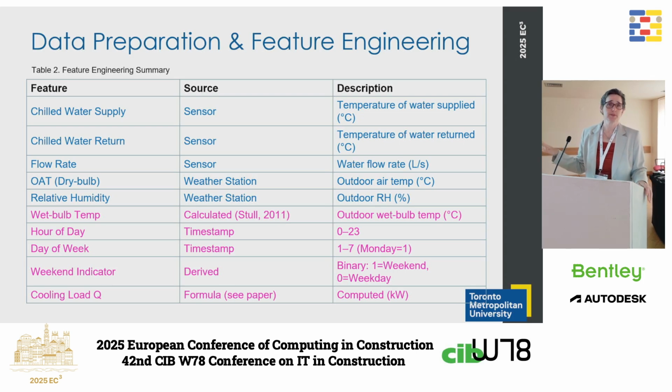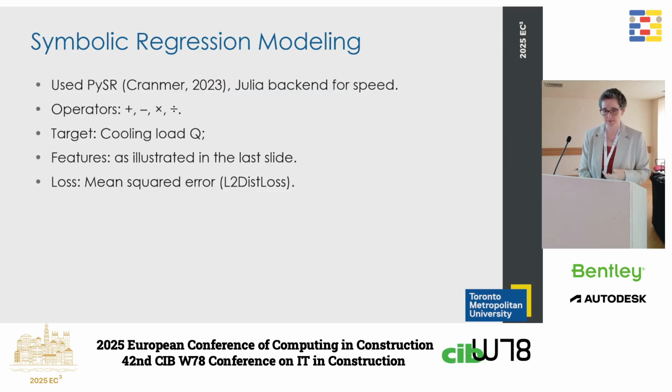This cooling load that we have, we didn't put the formula down just because of the space, but it's very simple, it's sensible cooling load. m c_p delta T, right? So your loop temperature coming into the chiller minus coming out of the chiller, times your volumetric flow rate, times your mass, times your specific heat capacity of water. So it's very straightforward, and we're just looking to see what the load that the chiller actually sees is, because that feeds into our chiller optimization model.